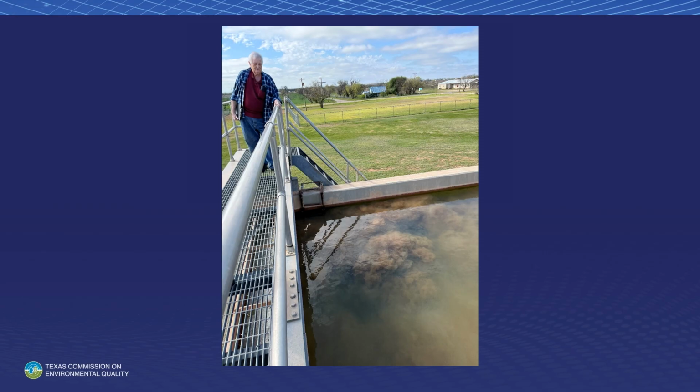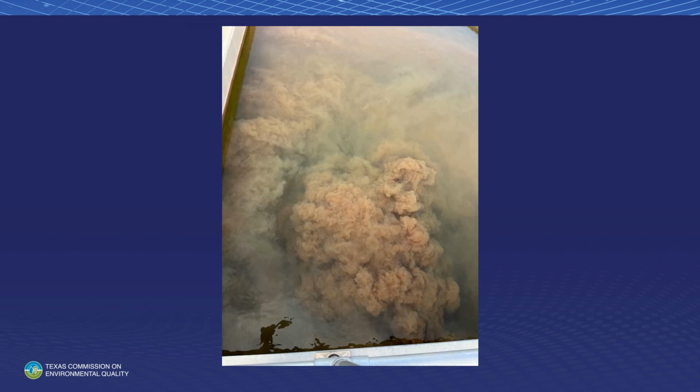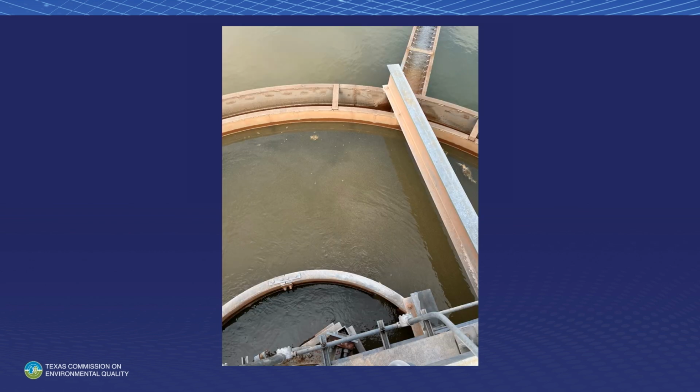Oh boy, this was just recently. Do you see that sludge blanket right there? This is a solids contact upflow clarifier, and this is the south side of the blanket. I'll give you a little closer view of it. That's what it looked like. This clarifier was running, and it looked just like that on the south side. On the north side, it looked just like that.